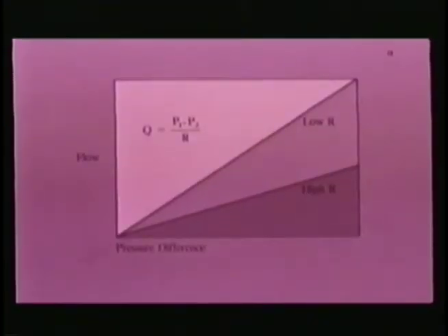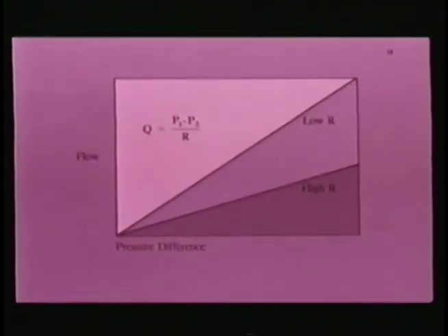18. In streamlined flow of a simple fluid through a rigid tube, the relationship between pressure drop and flow rate is linear. At a given pressure difference, the higher the resistance to flow, the lower is the flow rate. The factors contributing to resistance and the mechanisms of energy dissipation are the subjects of the following discussion.